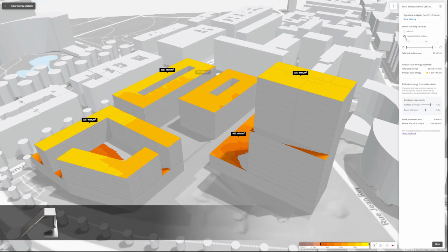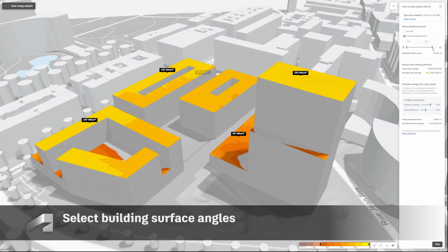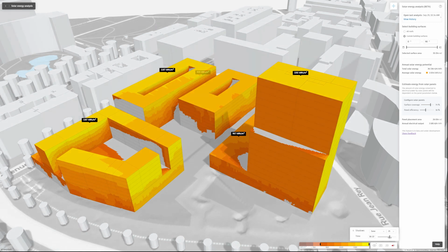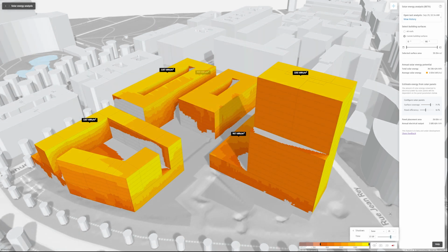The solar energy analysis in Forma reacts to whatever geometry you have put in your project and immediately tells you the annual solar energy potential as a factor of kilowatt hours over a set area like square meters. This is a starting point to start exploring your options. Would your facades be best suited for heavy thermal insulation, sun walls, or do you see potential for a solar panel system? You can of course opt to only consider roofs or any surface or filter based on a specific inclination.